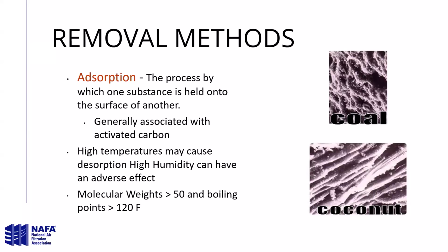Adsorption. You can read it. The process by which one substance is held onto the surface of another. It's generally associated with activated carbon. And it's a surface effect. Have you ever taken a balloon and kind of rubbed it on your head and seen it stick to the walls? That's van der Waals forces, and that's exactly how chemicals are attracted to activated carbon. There's a little force there where it attaches to the surface of the carbon, and in fact, it doesn't stay on the surface. It then goes into the pore structure where it becomes liquid again.